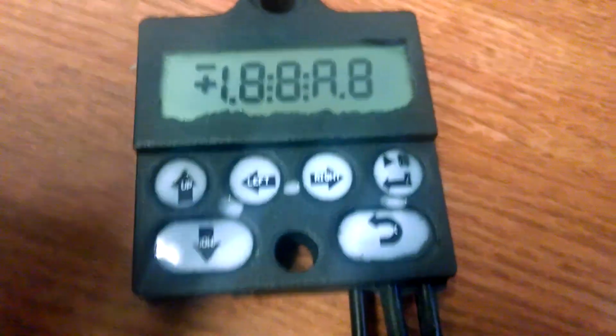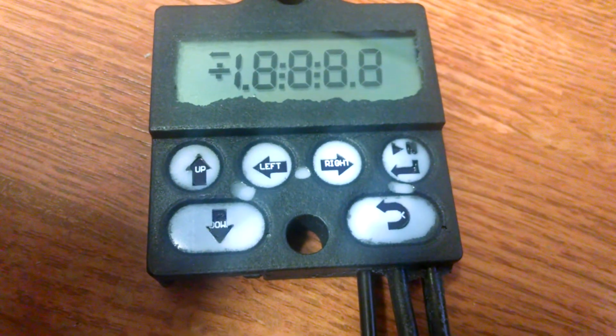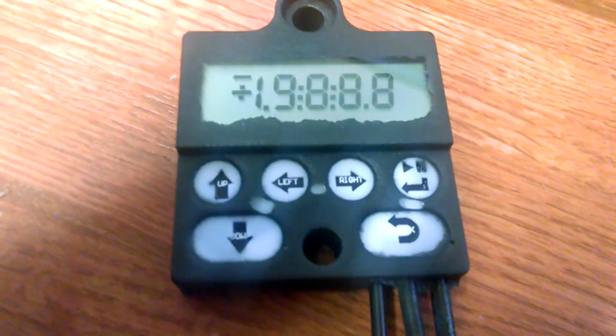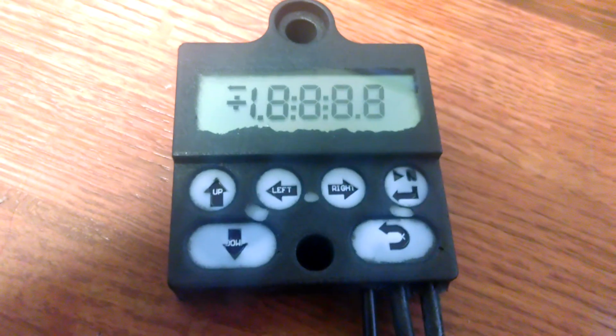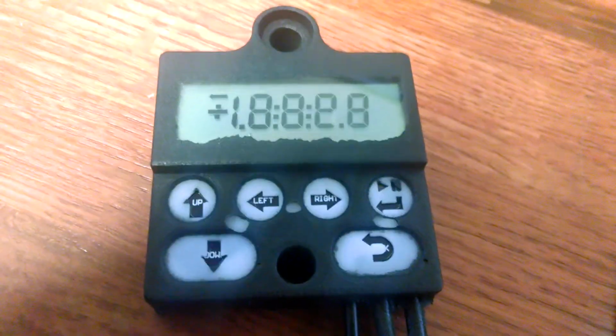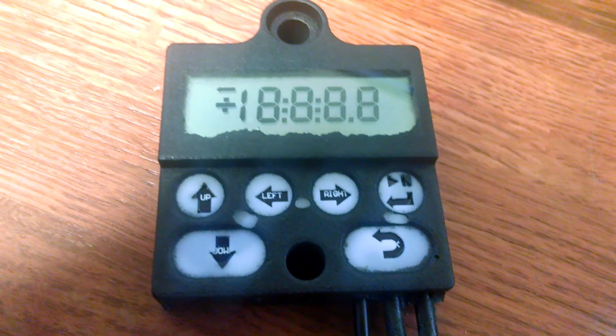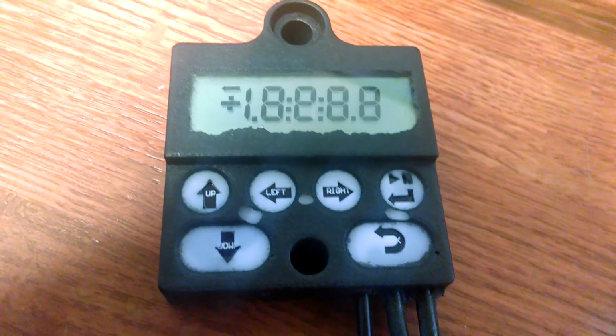You just run the sketch, and then you can run the generator.py script, and that will actually generate the libraries and all the segment maps on the fly for you. That way it works with pretty much any 7-segment display.